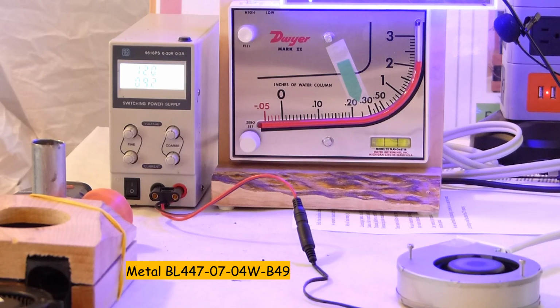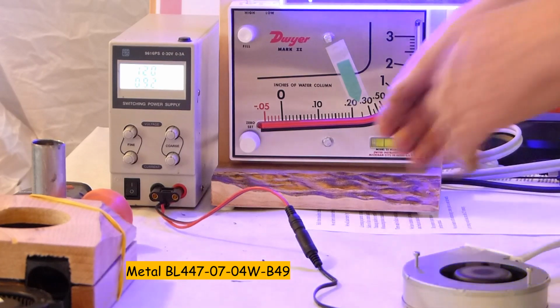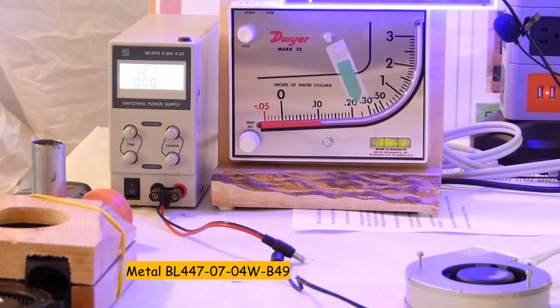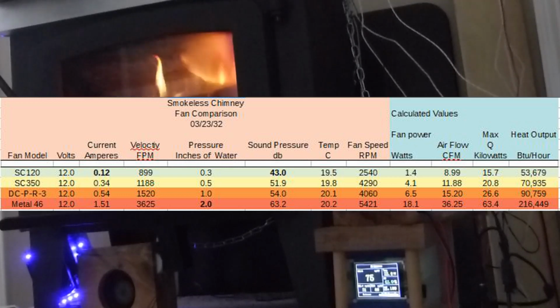We've showed you about fans, and fans are one way to control combustion air. You have to get the pressure and the flow right. We presented a spreadsheet and how we got the parameters for each fan and how flow rate affects the maximum heat release rate you can get from a fan.